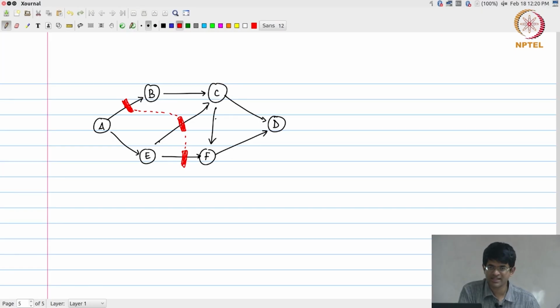In other words, all that I am saying is this is a valid pipelining transformation. Will this solve my problem? Not really, because what will happen over here is I will end up getting the slightly longer critical path over here. Okay. But this is still a valid pipelining.